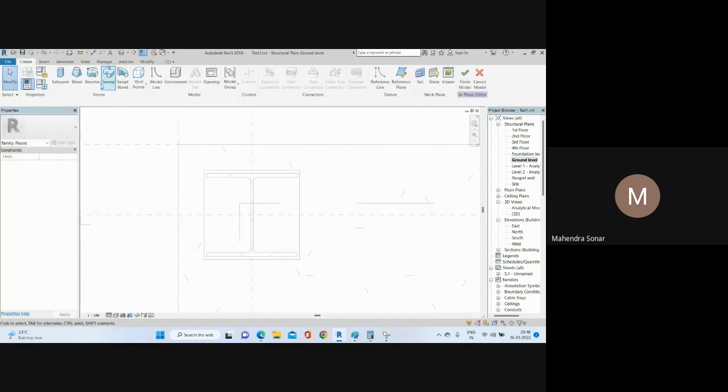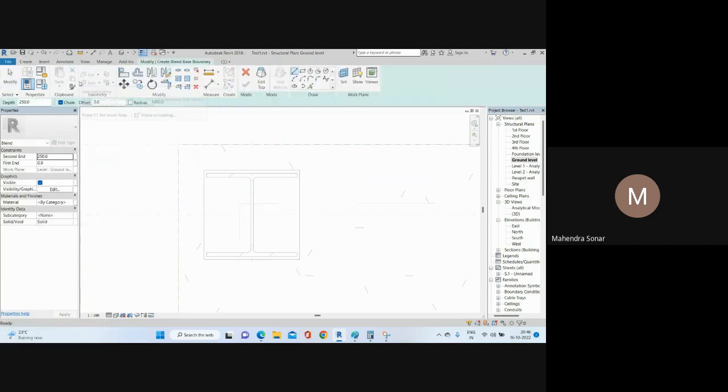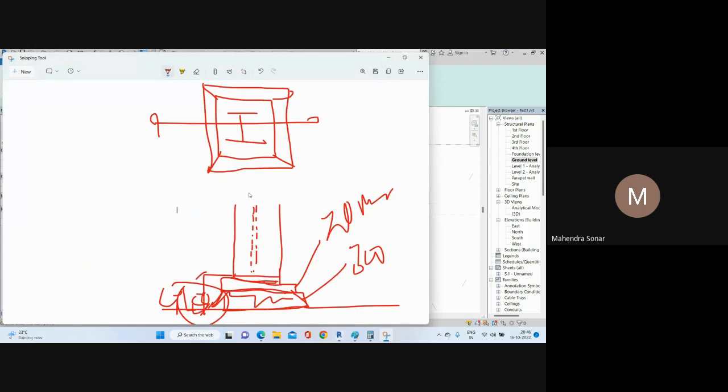Then after that you need to select this option, solid blend, and just select. So you can see once I select this, you can see here edit top. It means you are in bottom, right? So in that case, we need to add the two squares, okay, like that. So this is the bottom plane and this is the top plane. Okay, so you need to give your top plane to just match your base plate. Okay, so your grout starts from this point to this point.